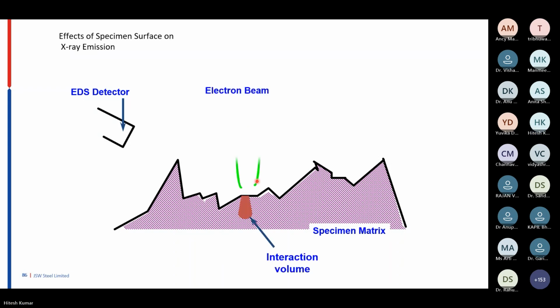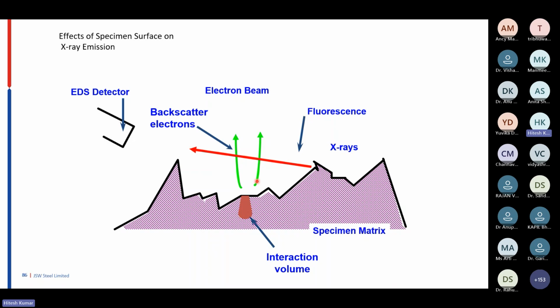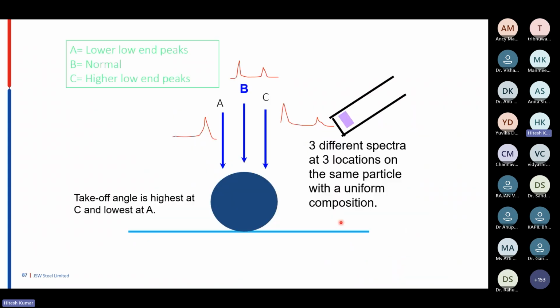You can see these are the X-rays which you basically use for the EDS detectors when electrons are bombarded on your sample. These are the absorption of X-rays. So you need to prepare your sample. Sample roughness basically plays an important role. The surface or sample preparation should be there. That's why, as we talked about uniform coating as well as metallic samples, the sample surface preparation should be proper. Sample preparation should be done in the proper way.